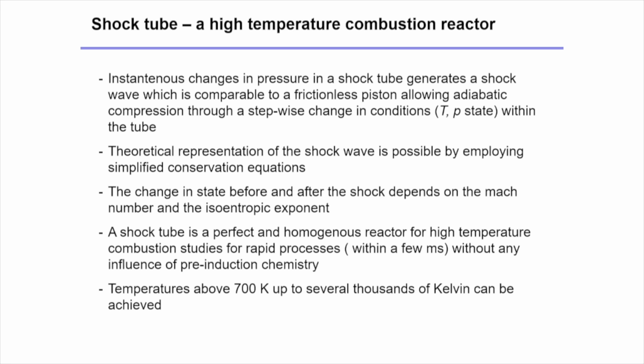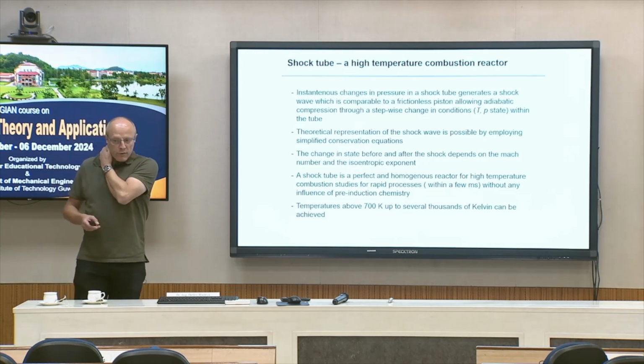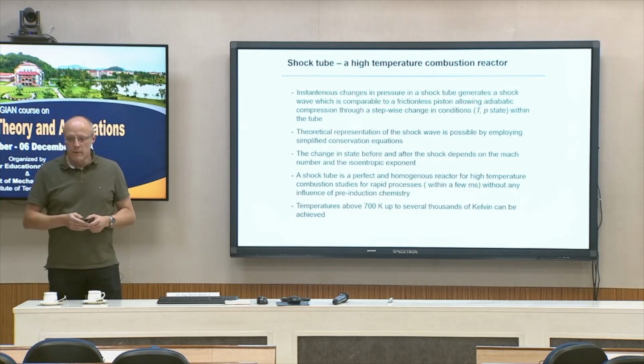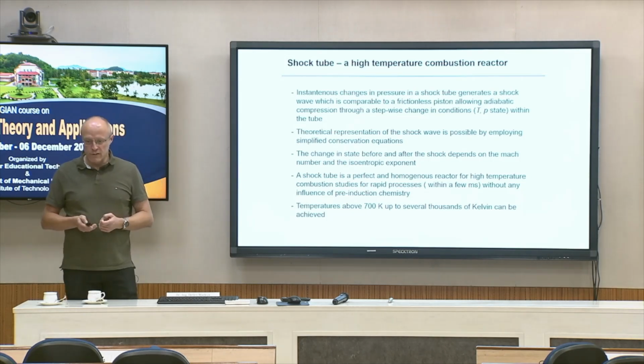So a shock tube is a high temperature combustion reactor for our application. Not for your application here in Guwahati, but for our application. So we have an instantaneous change in pressure. This generates a shock wave, which we can compare to a frictionless piston. So we have a shock wave moving through our system, and this compresses our gas adiabatically. So we have hopefully a stepwise change in temperature and pressure at a given position.